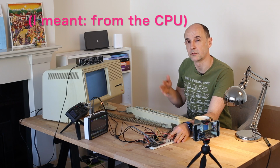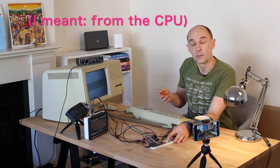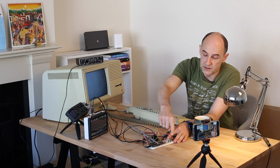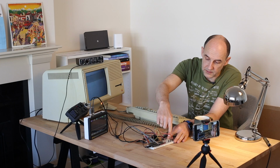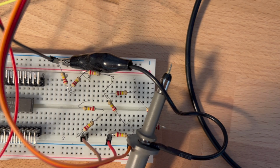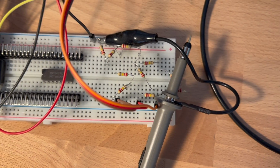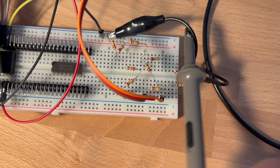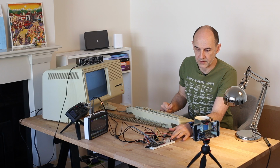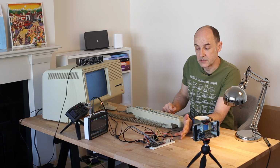Similarly to how it's done in Lisa, 3 digital lines coming from the VIA go to the resistor ladder to control the volume, and the programmer has control over those 3 digital lines. So 3 digital lines are connected to what looks like a cobweb of resistors, but they are actually arranged in a ladder pattern. I'm going to share the schematics for that in my article linked below. But let's see how that works.